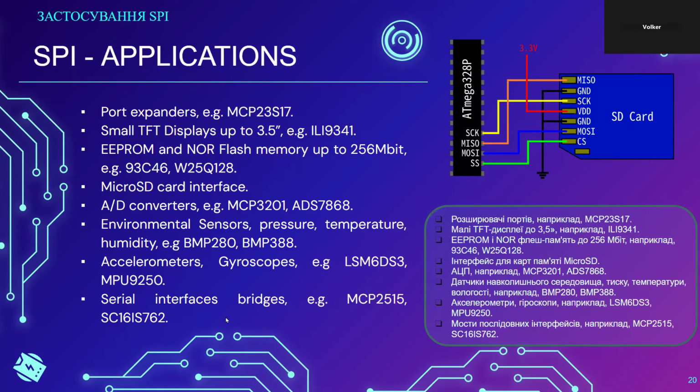It is a very convenient way of loading configuration data, even text data, from a PC onto the SD card, plug the SD card into your embedded device, have the microcontroller read this data from the SD card, and set up calibration and configuration data.